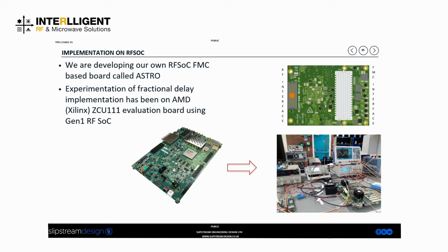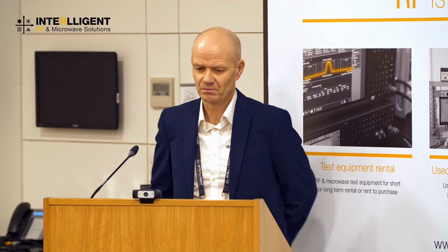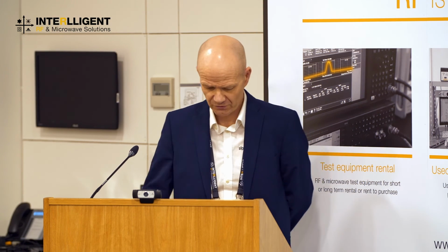So although we're developing our own RFSoC board, which is up in the top right, which we call Astro's little FMC-based RFSoC board, the experimentation work that we did here was on a Xilinx ZCU111 Gen 1 RFSoC board. There's a picture of it there, and there's a picture in the lab of a couple of boards. Part of the challenge with these types of things is making them work together, so synchronizing multiple devices to work in synchrony, whilst maintaining coherence between all the outputs. So that's why we've got two boards there.